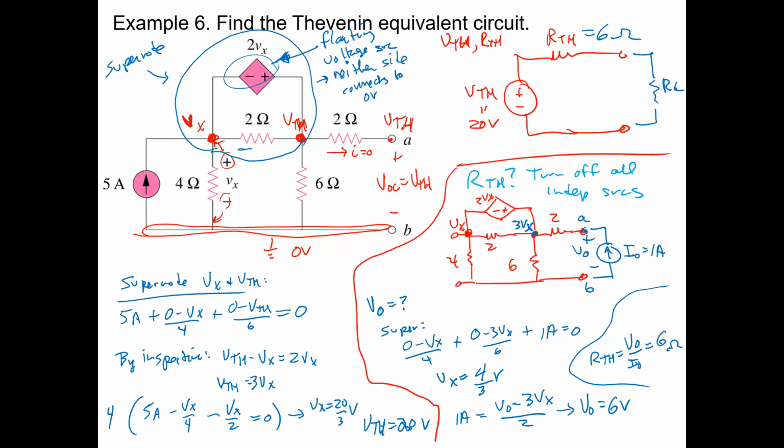It just happens that this dependent source wants to have a 2Vx voltage drop between its 2 terminals, and we have Vx on the bottom terminal, so the top terminal still has to be 3Vx, because 3Vx minus Vx gets you 2Vx. It's a property more of the dependent source that hasn't changed, rather than any of your analysis from the previous section. You know what I mean?